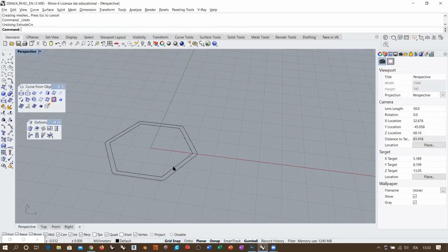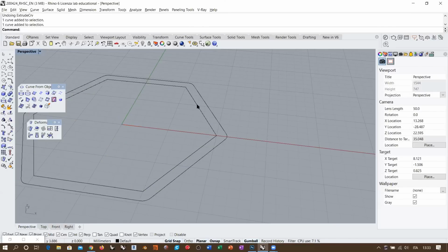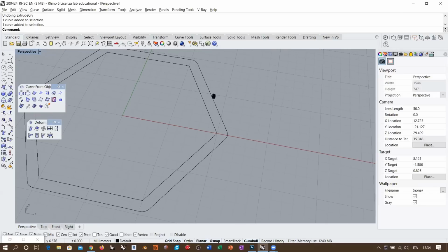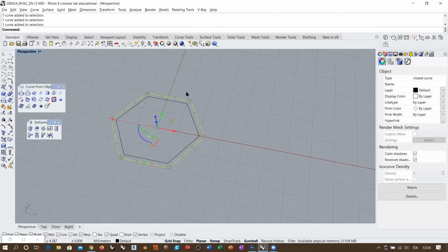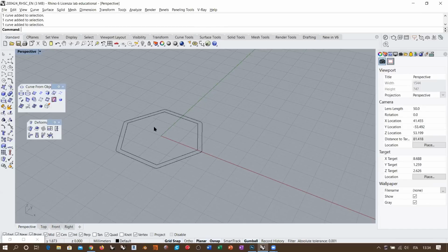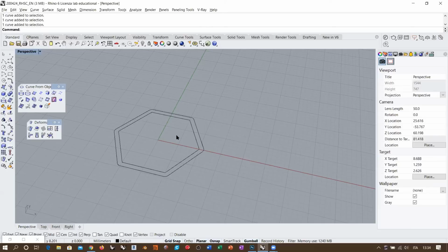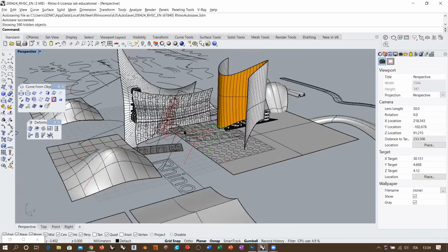So if I extrude this thing here, I will get, oh, by the way, this is still a thing. Yeah, okay, I understand, because this is still maintaining the idea that this was a linear side, a linear polyline. So it maintains this linear aspect, and therefore there is a curvature discontinuity that results in an internal edge. You can eventually merge surfaces and so on in order to get to a more regular result. But it is important that you do this with a smooth corner, for example, when you offset this thing.